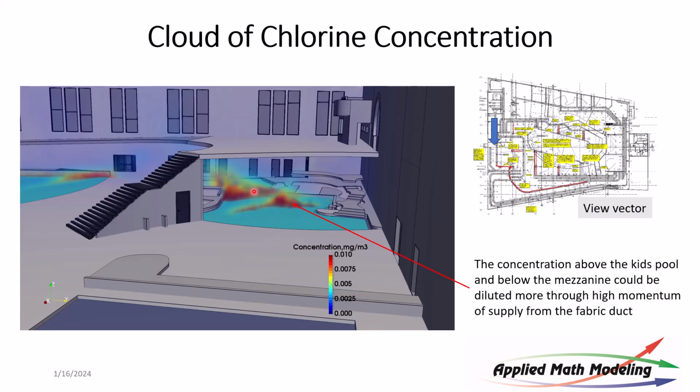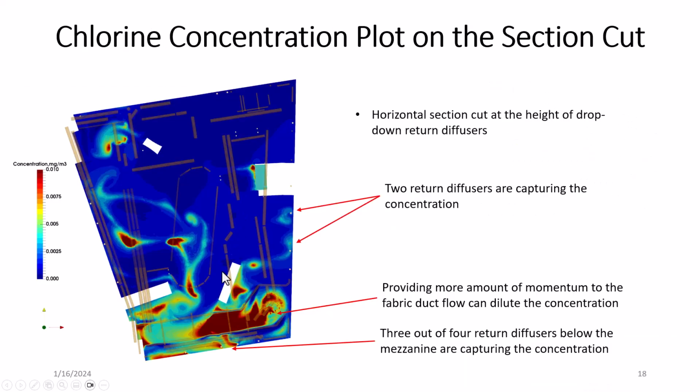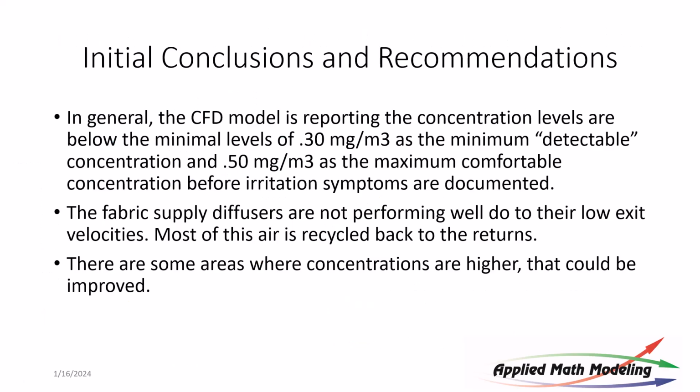The kids' pool area had a little bit more than some of the others. And you can see from a top view, this is a slice. We're looking down at the environment at a particular height, and you can see the concentrations in some areas are higher. And so you adjust your positioning of your diffusers and of your HVAC system to try to minimize that. Very good application of CFD for an indoor water park.